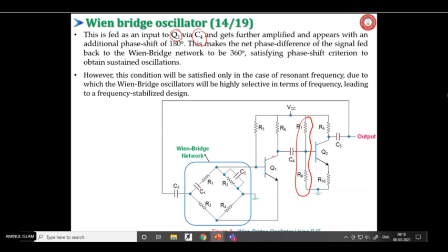It's the voltage divider bias. You need a particular voltage value here. That voltage value is created by this voltage divider, right? Maybe here you need, say, 0.8 volt. I am assuming roughly without any particular logic.